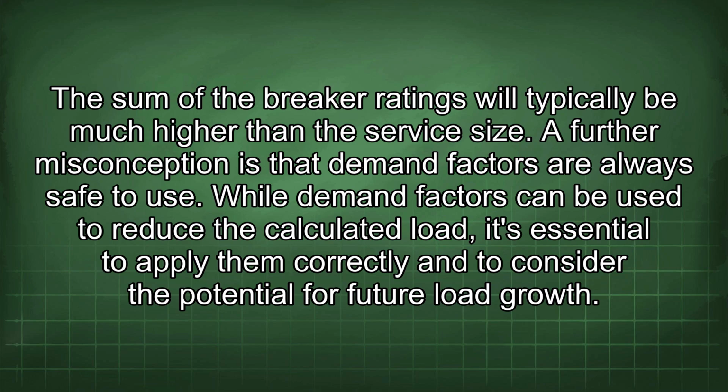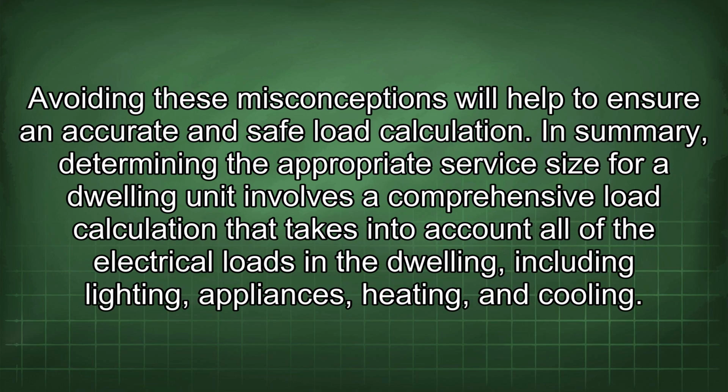A further misconception is that demand factors are always safe to use. While demand factors can be used to reduce the calculated load, it's essential to apply them correctly and to consider the potential for future load growth. Avoiding these misconceptions will help to ensure an accurate and safe load calculation.